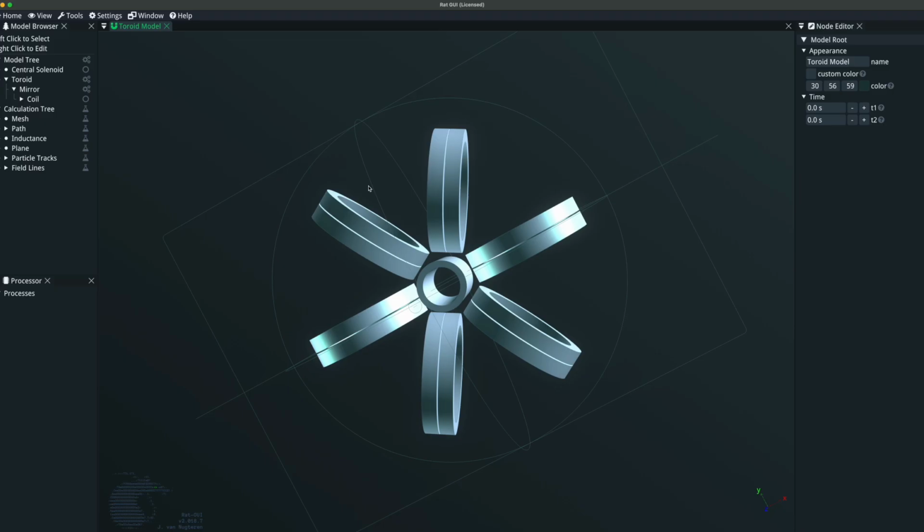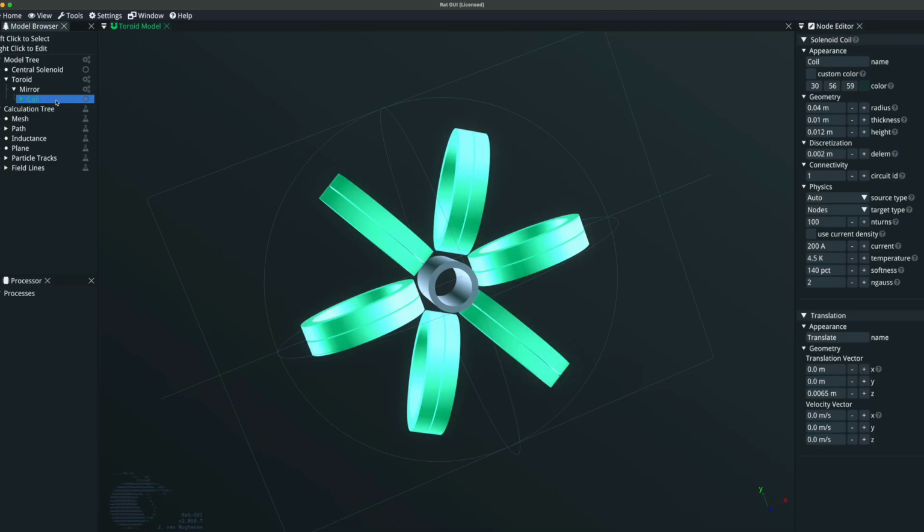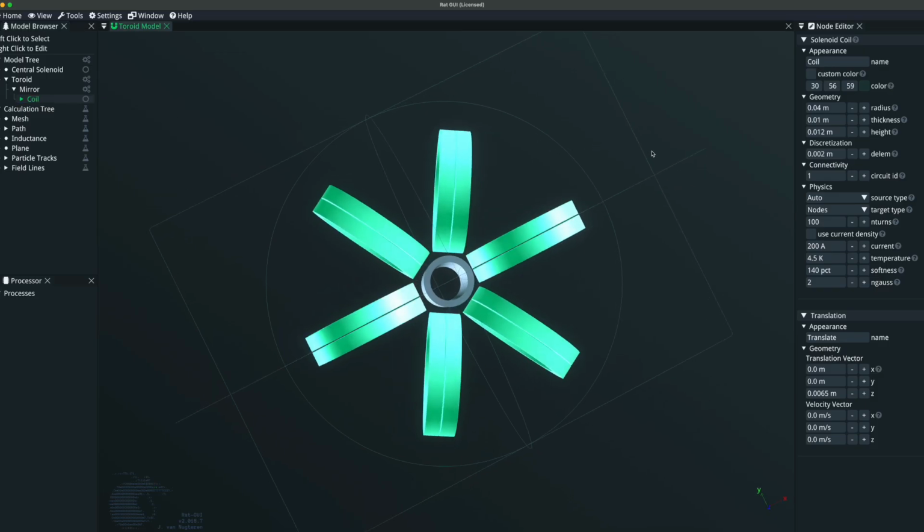video list basically. And so in the first tutorial we will explain the multi-level fast multipole method, and then you get a feeling of how the settings of element size affect the speed of your calculation. But the other thing that affects speed and also accuracy of the calculation is the source type.